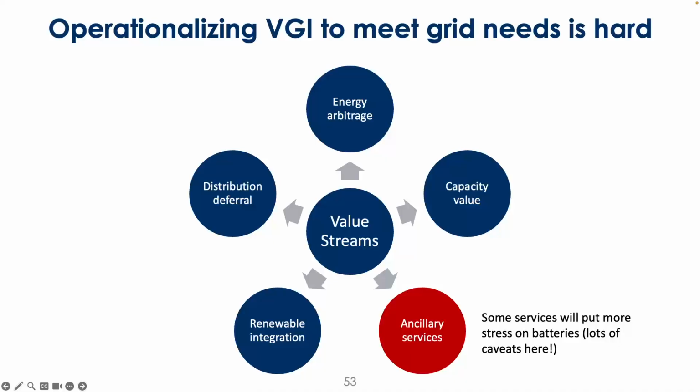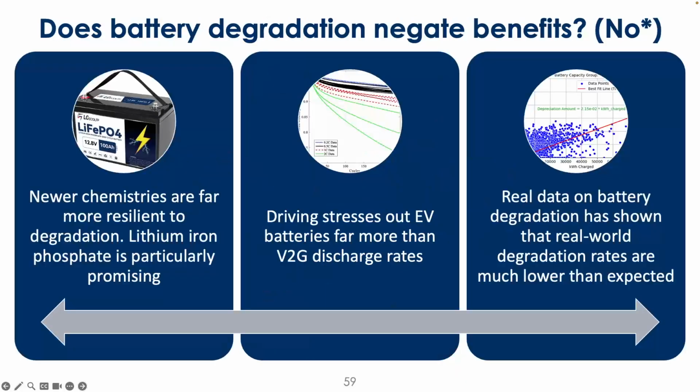And so that's kind of an open question. So with that one in particular, I actually have a little slide on that. Does battery degradation actually negate the benefits of participating? Probably not. Newer chemistries are a lot more resilient to degradation, right? We talked about how lithium iron phosphate is very resilient to degradation.